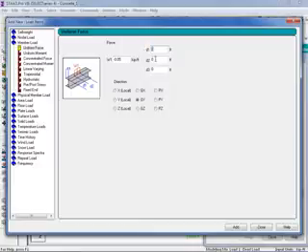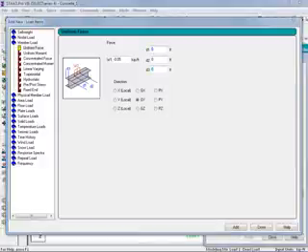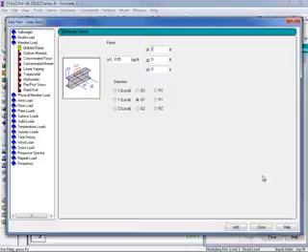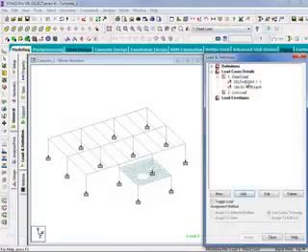Now if I set all these d parameters equal to 0, this is going to be a uniform force along the entire length of the member down the center line of the beam, which for this particular model would be appropriate. If I also look in this graphic, you can see that I can actually use these parameters to specify other different types of loadings. Once you enter all of your uniform force items, then I'm going to go ahead and click the Add button followed by Close, and here I can see that the two load items that I created within that dead load case are now available. The question mark in front of each type of load indicates that this is the type of load that needs to then be manually assigned to my model. So that would be the next step.